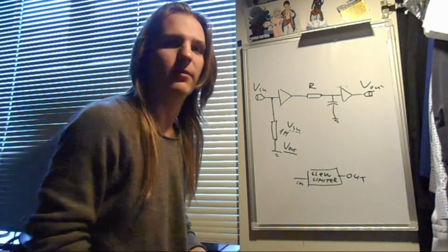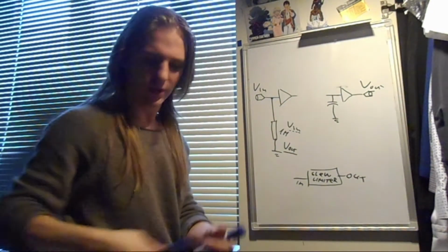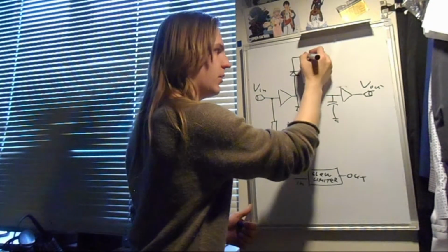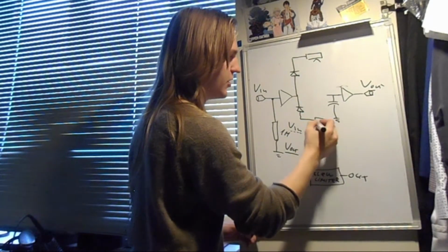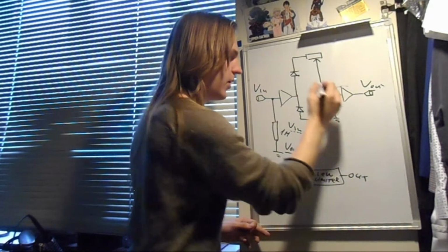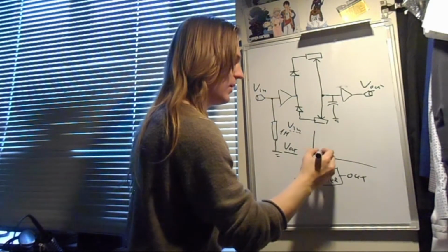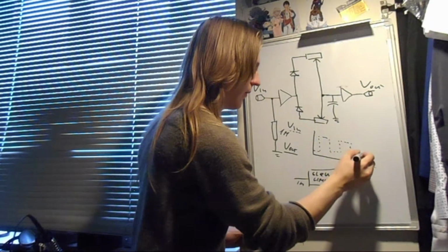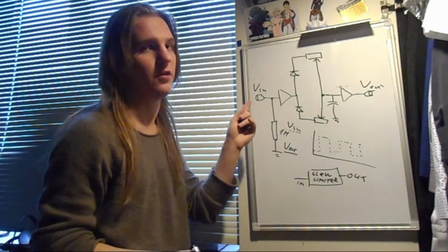One modification we can make to this thing is replacing the resistor with a network: a diode right there, a diode right here. Put our potentiometer 1 here and our potentiometer 2 there. Connect them and put them into the capacitor. If we input our square wave, again, I'm looking at the square wave situation simply because it's very simple. It can be anything you want.